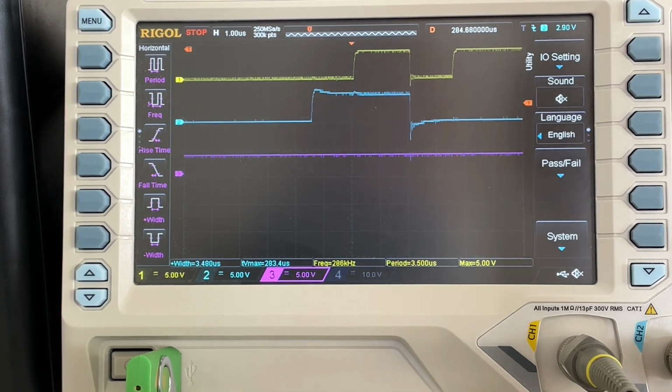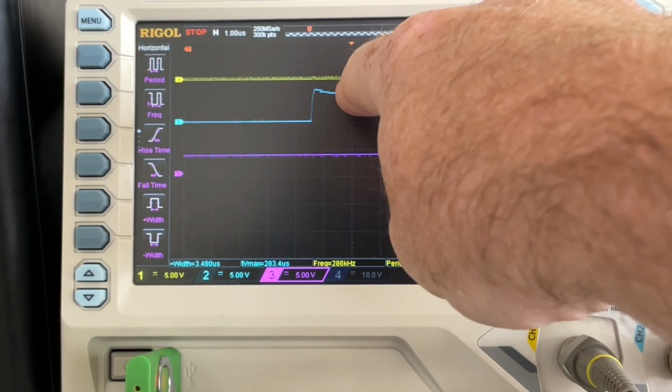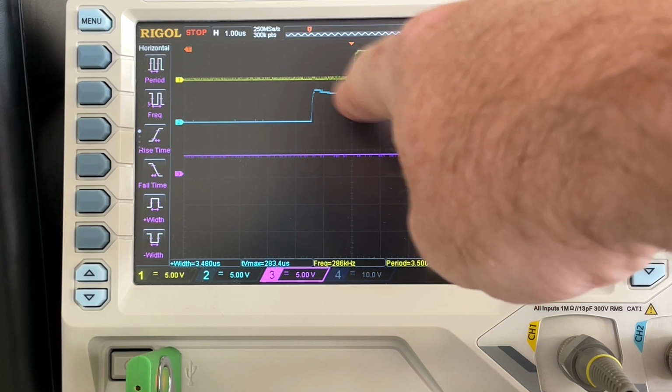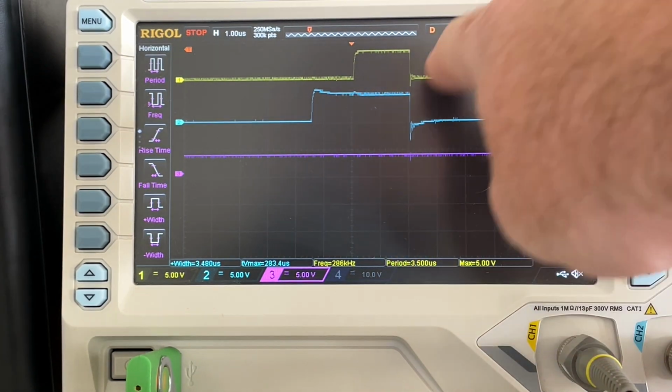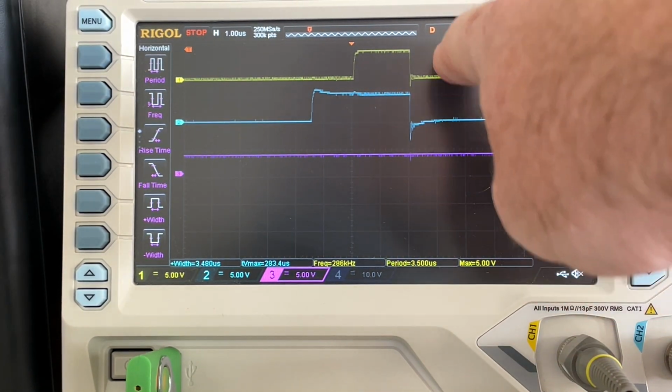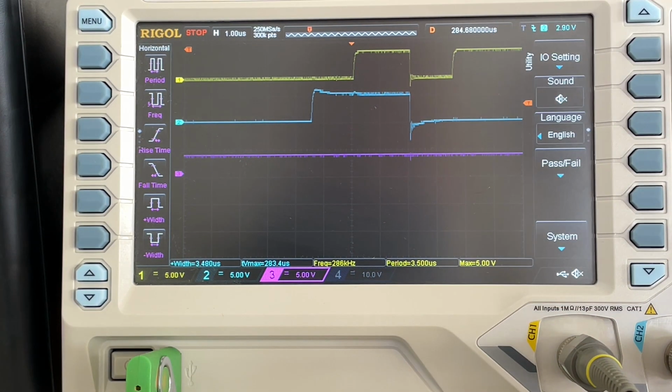The data levels are already set, so that when that clock goes up, it's like, okay, that's what we want to be a 1. But the next rising edge here, we want that to be a 0, so it sets it down after the clock's been set. So that's what the signals look like on the wire.